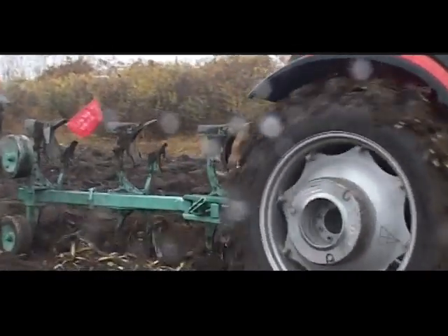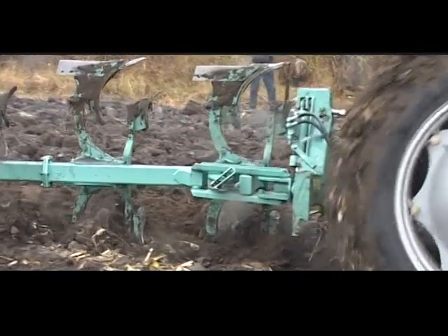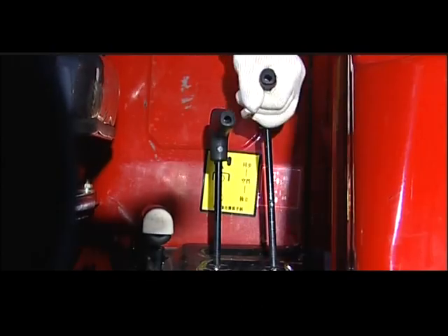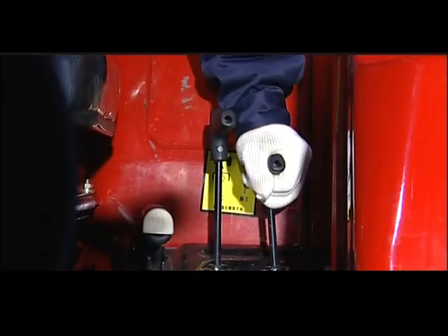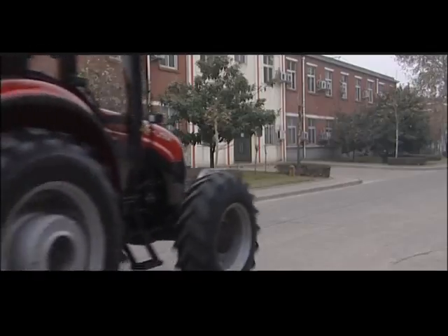When the tractor is for running in at gears low 3 and 4, engage the front drive axle. Disengage the front drive axle when doing running in at other gears.